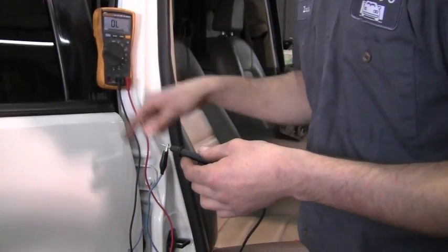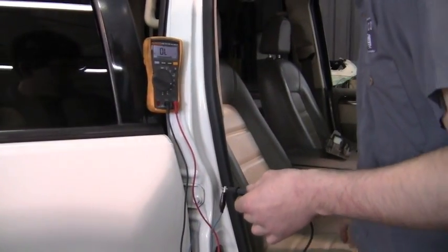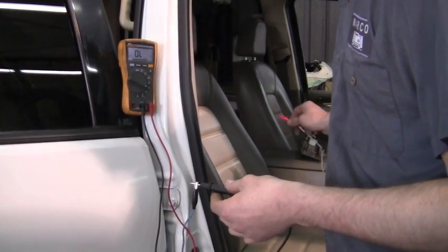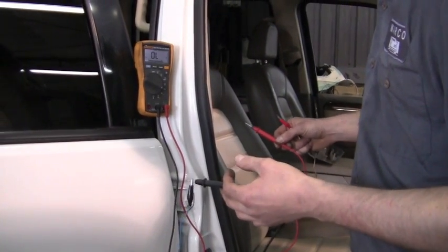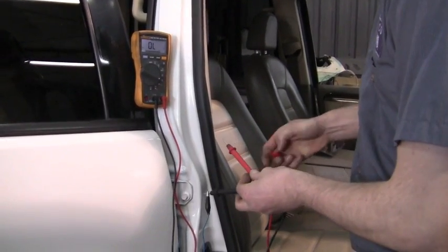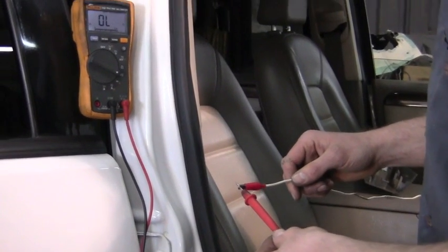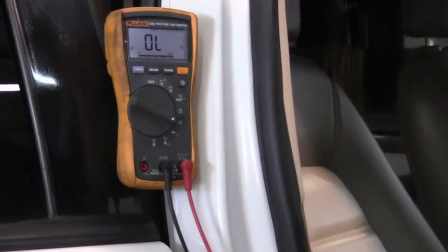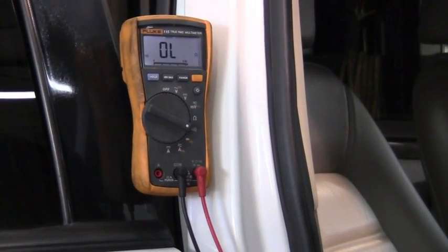Now our blue wire is back probed into our yellow and black wire on the right rear window switch, and our white wire is back probed on our driver's master switch yellow and black wire. So now when we touch the lead to the white wire, we should get good continuity. Now as we can see on our voltmeter, we don't show any continuity. We're showing out of limits, which means on this wire, if we have it connected correctly through the circuit, has an open in it somewhere.